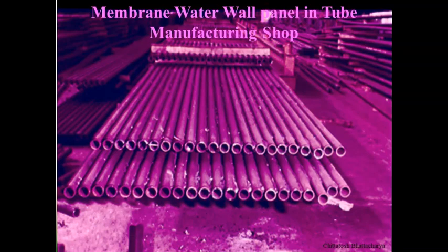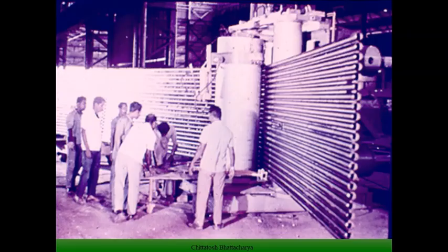But as there is only addition of latent heat of vaporization, the entire water walls are supposed to be at constant temperature, because there is no rise in coolant temperature. So a constant temperature difference exists between the water and the tube metal temperature.